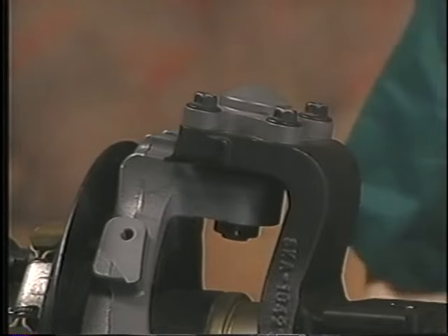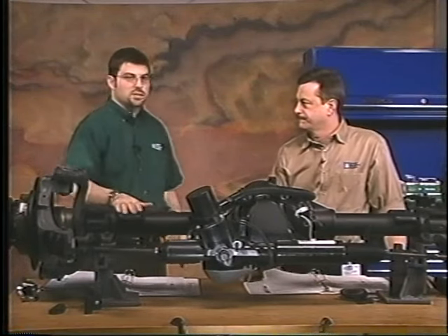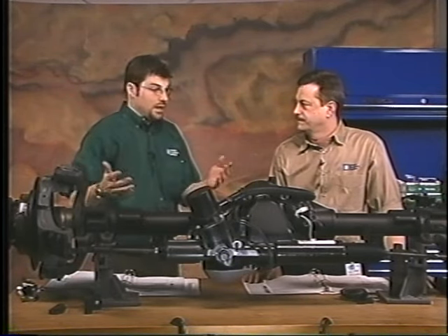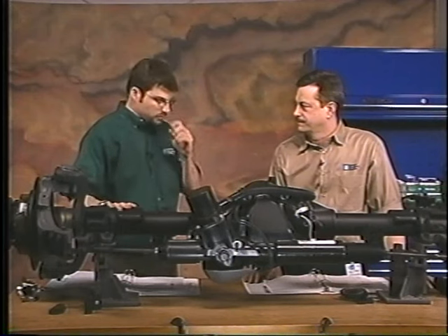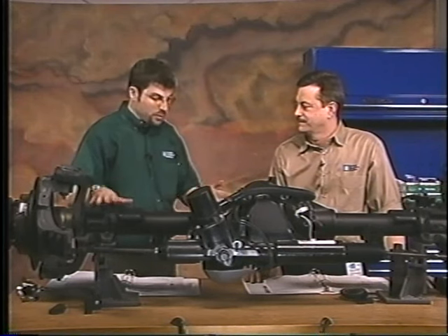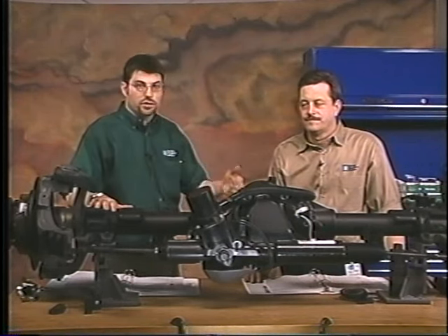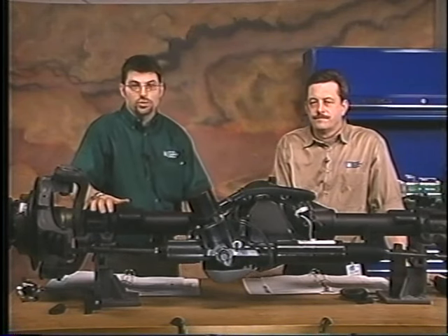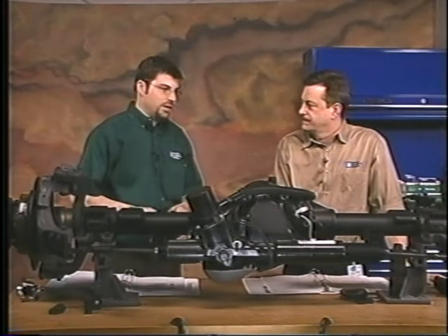All right, we've got to talk about angles too. The only adjustable angle on the system is toe. Set toe, let it go. Another important point for you today. You can adjust camber, can't adjust caster. That's why they also recommend not to shim the pinion to try to change the pinion angle, to correct for any launch shudder concerns. Because if you do, you're going to have an impact on camber and caster angles, which are non-adjustable. Okay, so we want to keep that in mind too.